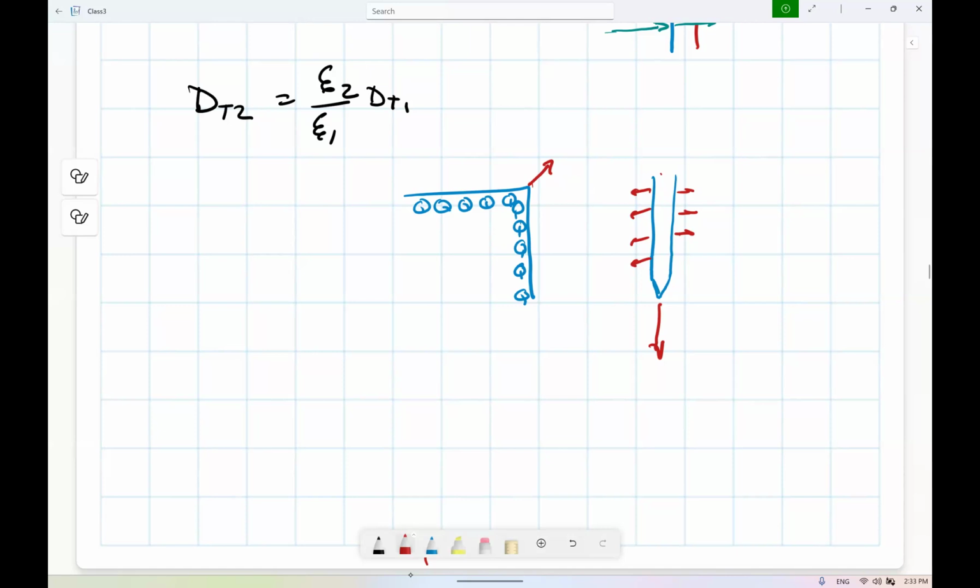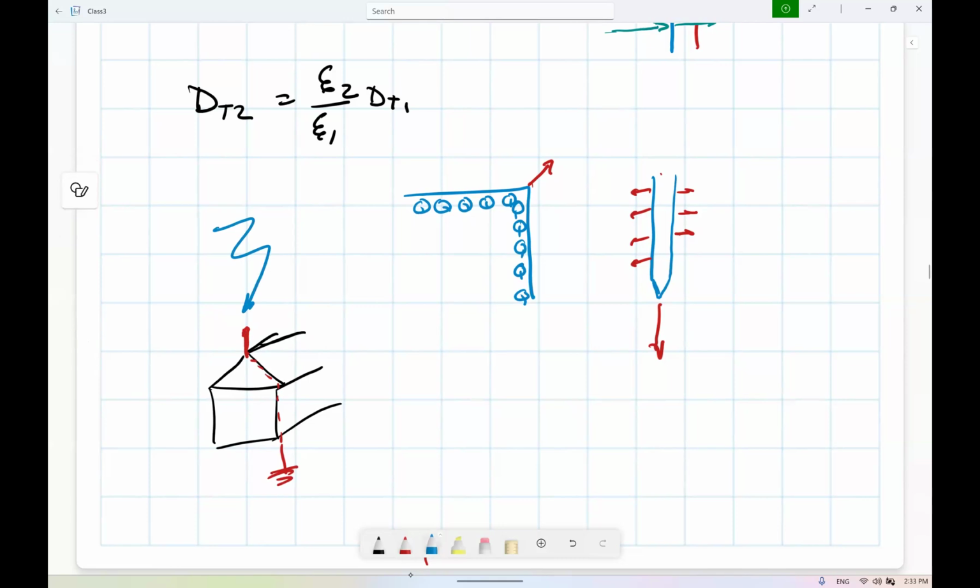The reason for that is the equation of the potential. You have a house, right? You have a house like this, and you want to protect the house. So you're going to have something coming out here, and this will go all the way to ground and it will be grounded. What you're doing, first of all, is elevating the ground. And what you want is the current generated by a lightning strike there to drain to ground. You don't want the current to go through the body of the house, right? So that's why you put that and you put it grounded.